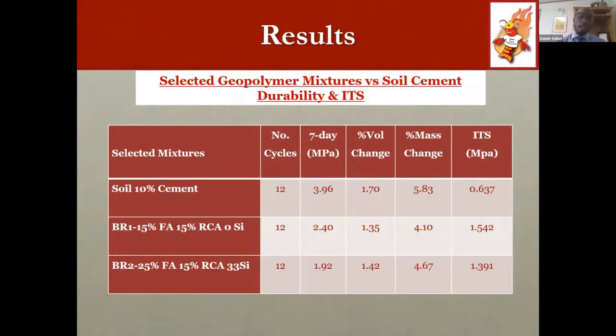Like I mentioned earlier, the high strain for the geopolymers determines the high ITS result that we achieved there. It shows that they have a better resistance to cracking than soil cement.